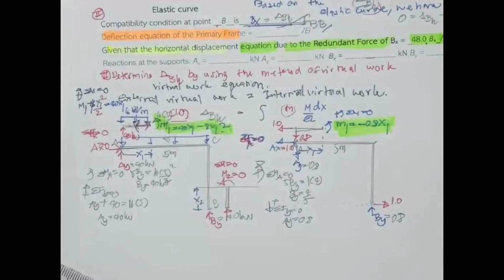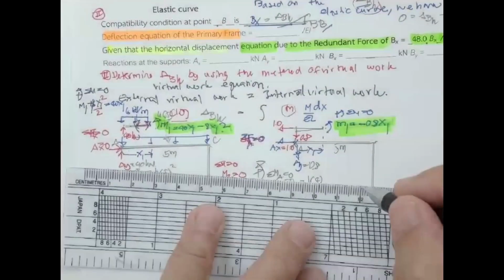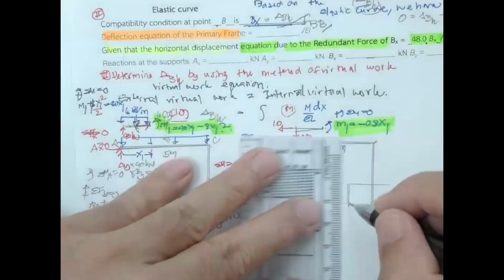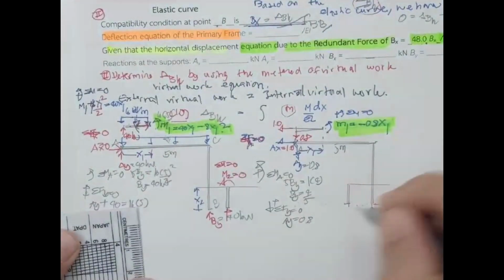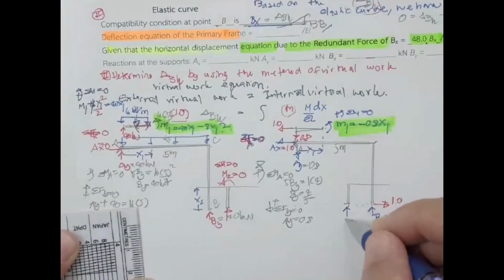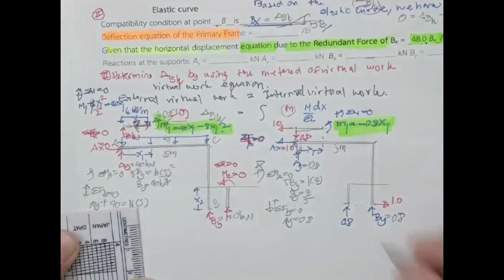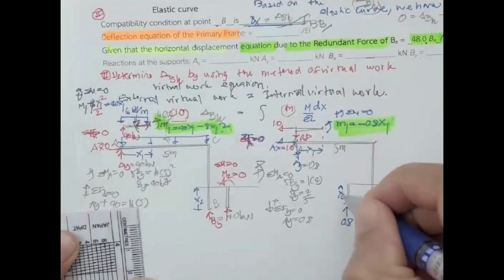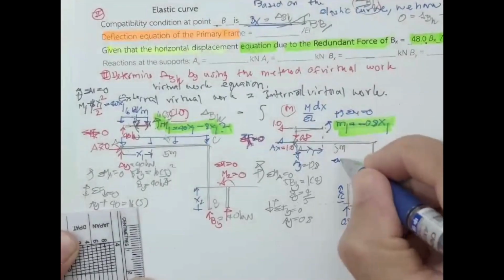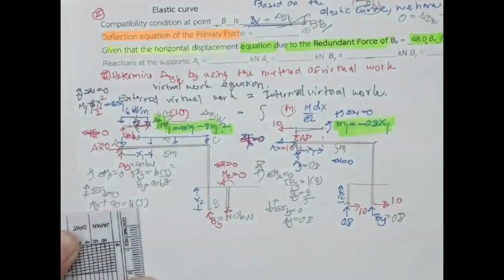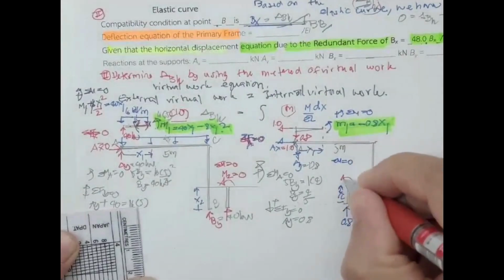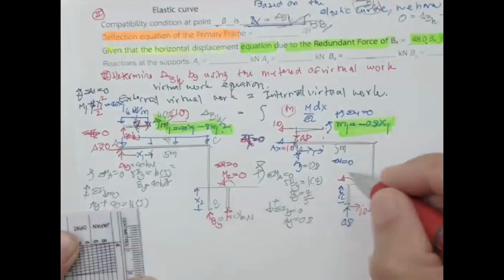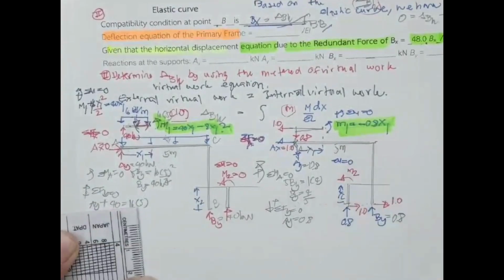And this is going to be your m1. Now, for this one, you may cut it over here and then this portion is subjected to the force of 0.8 and this is going to be 1.0 and this is going to be x2. You do the summation moment equal to 0 in this same direction, m2.